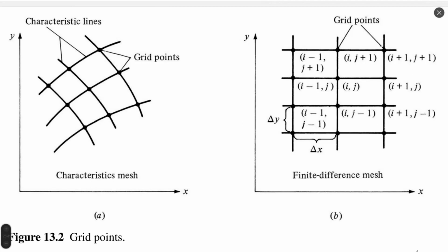So these two methods, the method of characteristics and the method of computational fluid dynamics, are both numerical methods based on transformation of a continuous dimension or continuous space into discrete points, grid points. In the case of the characteristic mesh, such a grid will be a result of calculation. We don't know this grid from the first moment of calculation. So characteristic lines or grid lines and grid points and parameters on cross-section of these characteristic lines will be calculated during the process